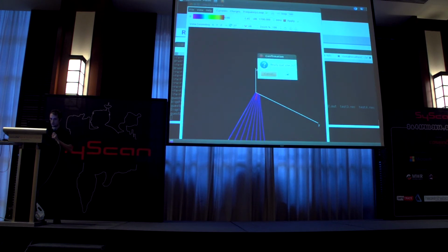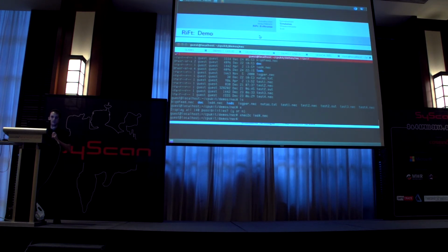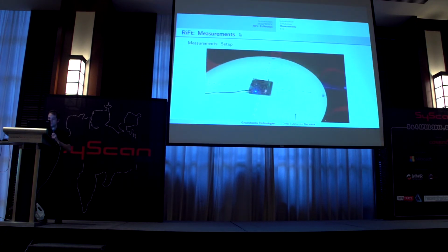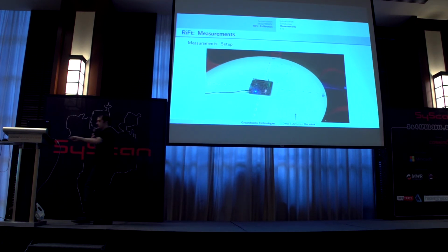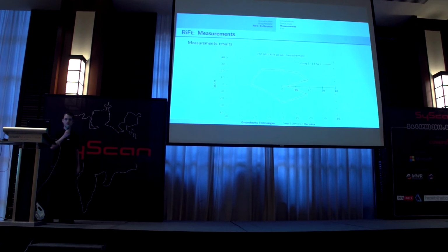I missed a lot, for example, I didn't simulate a ground plane that will modify the simulation somewhat, but it's just an idea of where the field points, basically. But I also ran real measurements to see if the field has this shape. So I put a table, put the board in the middle, and started measurements around the table, and the result is this. It's not really similar, but it's approximately the same.